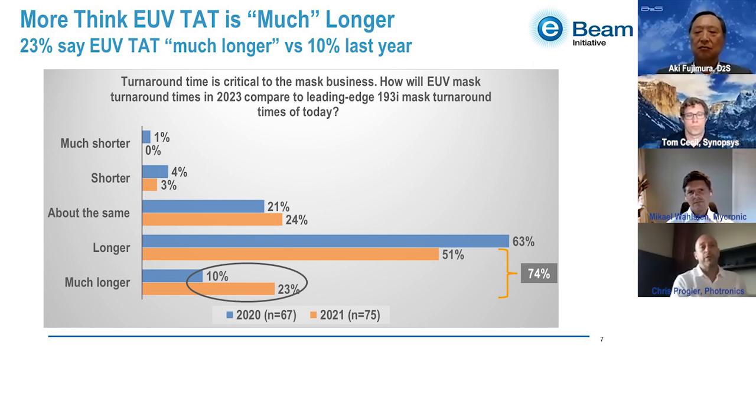The other place where productivity, I think, is taking a big hit is repair. We don't really have the greatest inspection capability for EUV yet. Actinic is just kind of hitting the world now. And repair is tough. It's a multi-layer stack. It's delicate. You've got absorbers that are different. And I mentioned earlier how important yield is in masks because the blanks are so expensive.